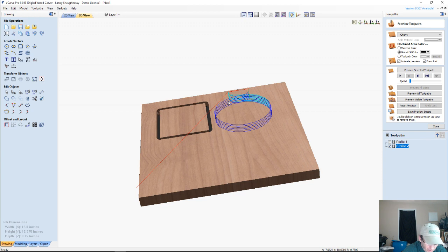I think a furniture grade Baltic birch, or furniture grade plywood in general that uses more veneers and better glues, is going to perform much better than a 4 or 5 ply plywood that I'm buying from Lowe's or Home Depot. I just think I'm going to get a better quality with a higher grade plywood.